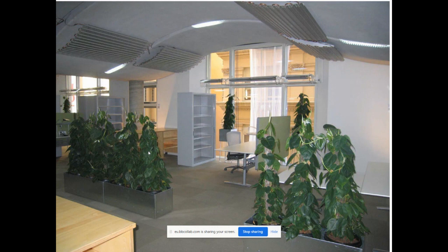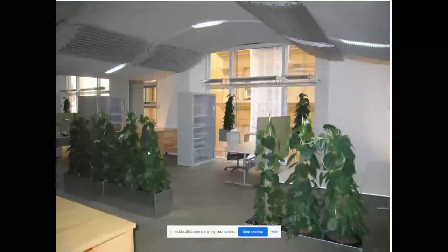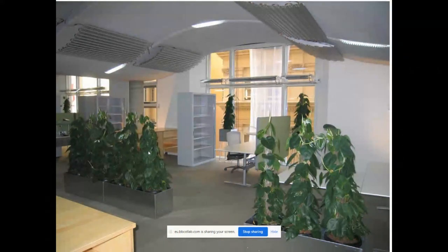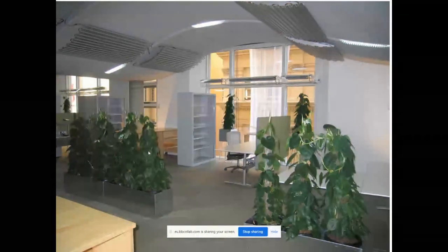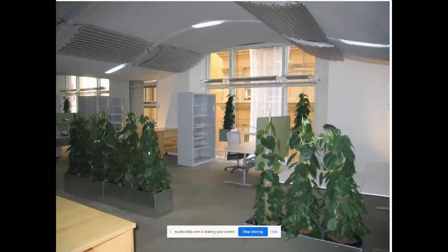and then the glass itself, we have used a reflector. It's low E glass, double glazed in Melbourne. Most of the light comes from reflected light. What we're looking at is on the south side of the building. That's the opposite to the equator in Melbourne. And strangely, the glare was much greater from the south because of reflected light. And the plants that we grew in front of the glass help to break up glare.